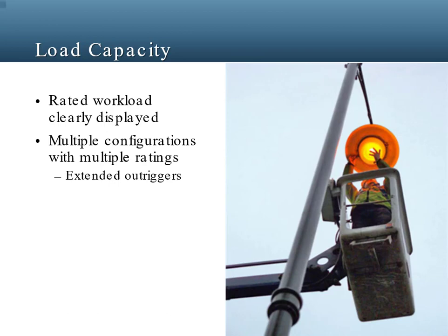Equipment with outriggers or stabilizers will have a different rating depending on whether the outriggers are extended. Obviously, the workload will be higher if the stabilizers are extended. Some equipment permits the use of different sizes of work platforms, so the workload must be listed for each type of work platform. Some equipment might have different rated workloads that depend on the angle of the boom.